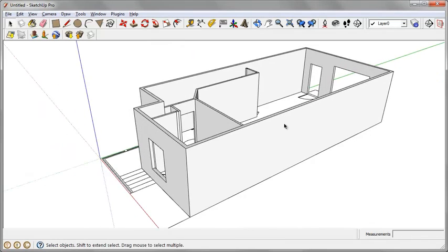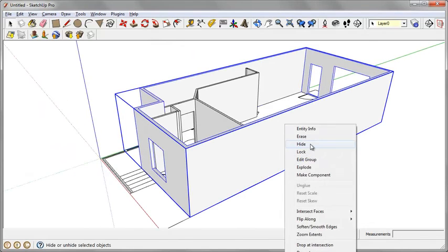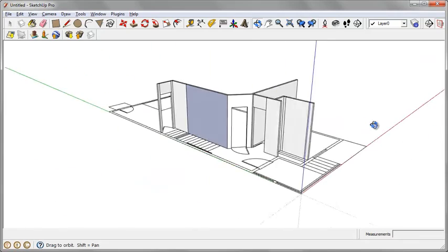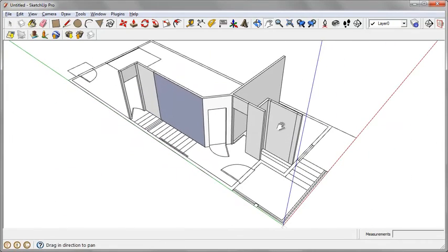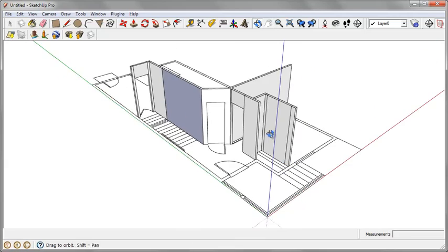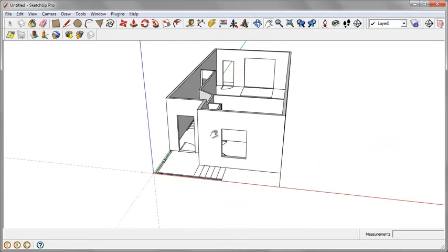And then also that gives me the ability to hide. I can right click on my exterior walls and hide all of those at one time. So the more groups you make in a model, really the more organized it's going to be in the end. So don't hesitate to make a ton of groups and really just break it down into the elements of your model, as far as like trees should be in a group, maybe shrubs should be in a group, walls and things like that. So that is how we can model off of a CAD DWG.